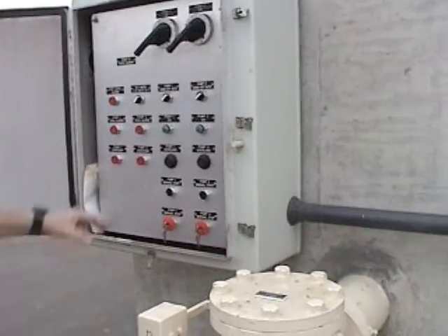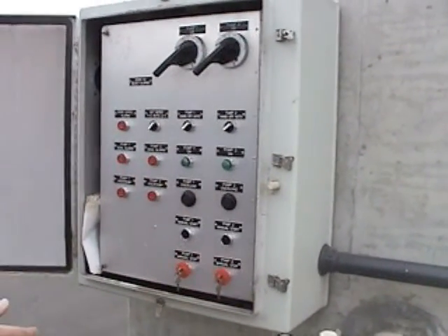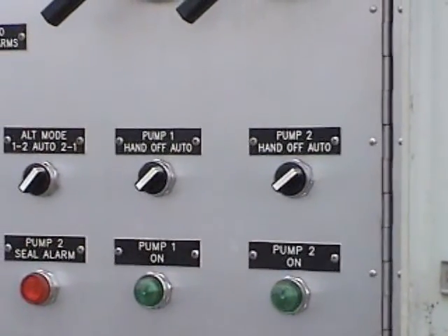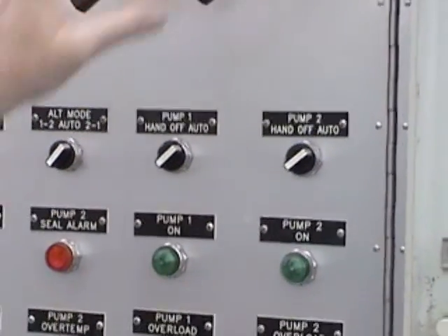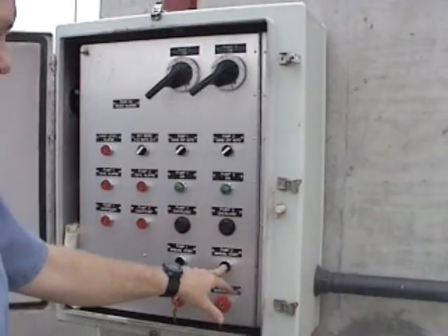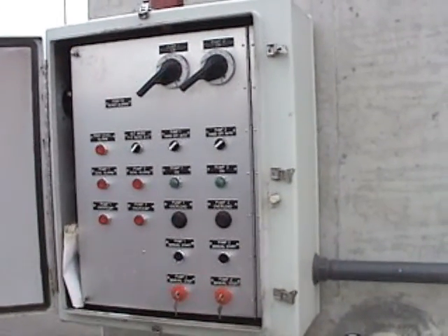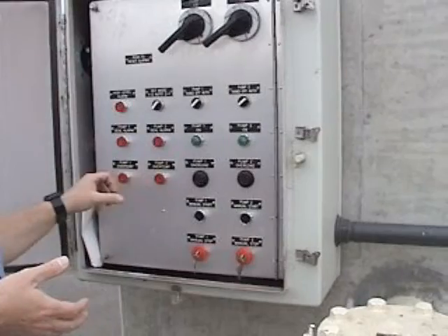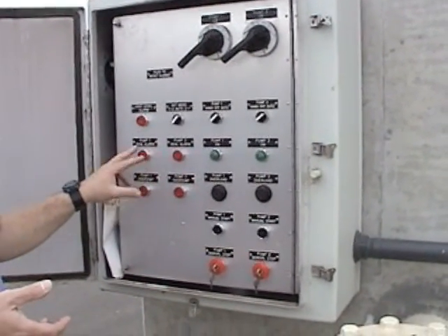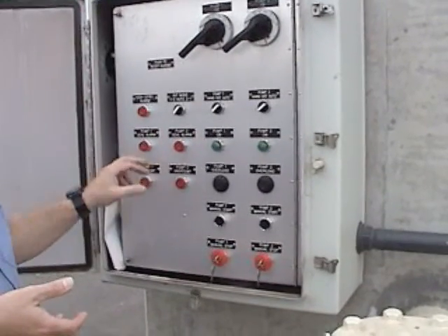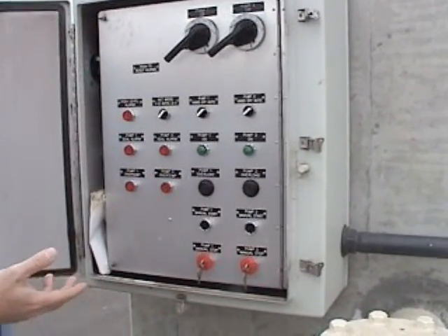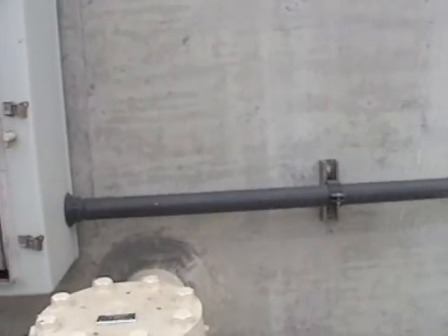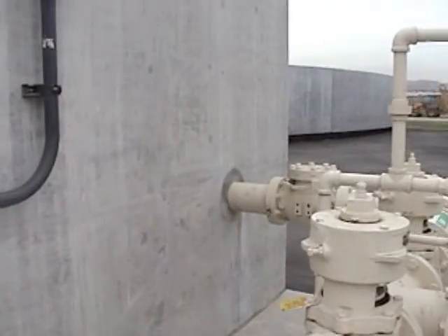So you want to check and make sure that this is in auto. Under normal circumstances, they should be in auto. If it's in auto but the pump isn't pumping, you can check for power, put it into hand, and manually start it. You should see the check valve come up. If it doesn't come up, a couple things could have happened. One, there may not be power to this panel right here. There's several alarms that you have, like over temp on the seal; alarms could be lit. Another thing that's happened fairly often here is there's some floats inside here, and when the solids are really heavy in this tank, they can keep the float from floating.